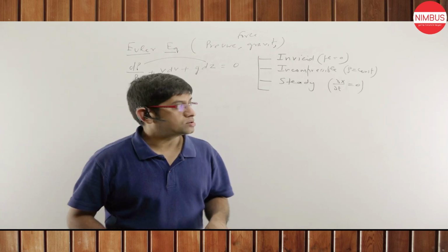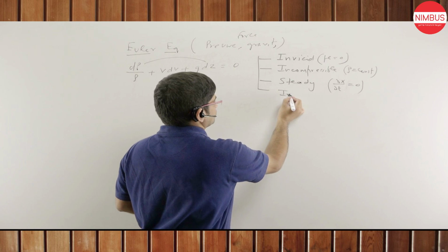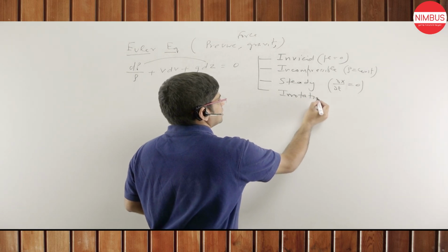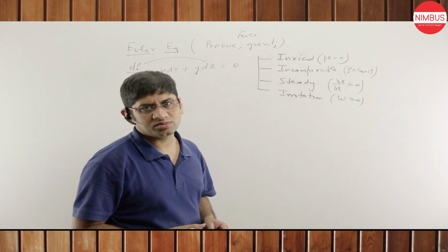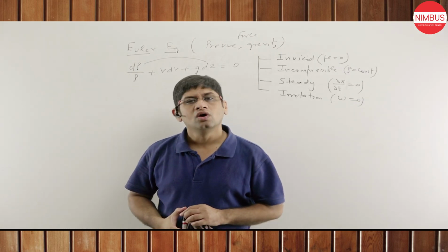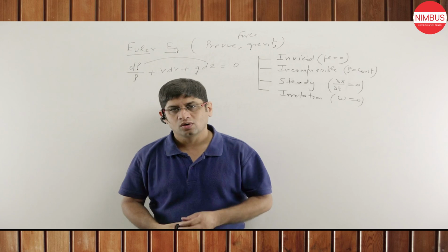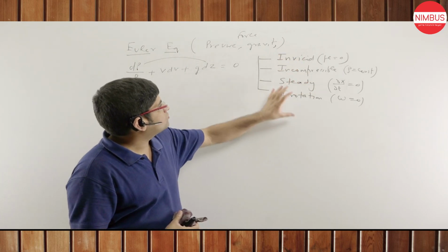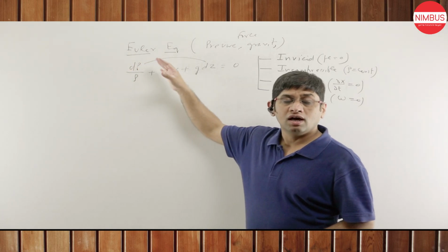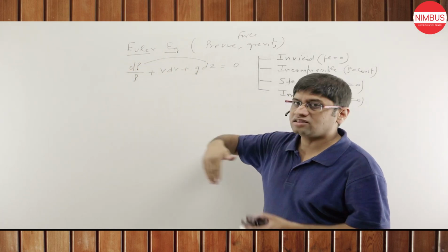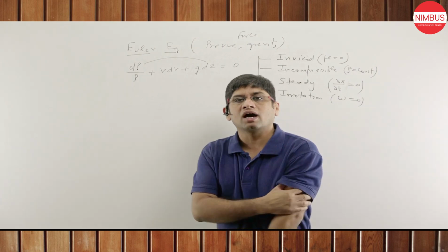And the fourth assumption is irrotational flow. So the omega terms, that is the rotational terms, will be 0: omega x is 0, omega y is 0, omega z is 0. So these are the four assumptions by which we make the Euler equation, and the Euler equation is the equation of motion, and there are two forces involved, and these forces lead to the fluid kinematics.